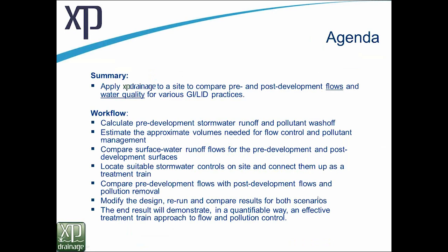Many times on a site, they can't, because in XPDRAINAGE we can bring in the terrain, the surface, the lay of the land. We built in a handy tool to just dump water on it. You can determine how much, and it spreads that water out. Where does it go? Where does it accumulate? Where are the lows? Where are natural areas that may be great, suitable for detention?